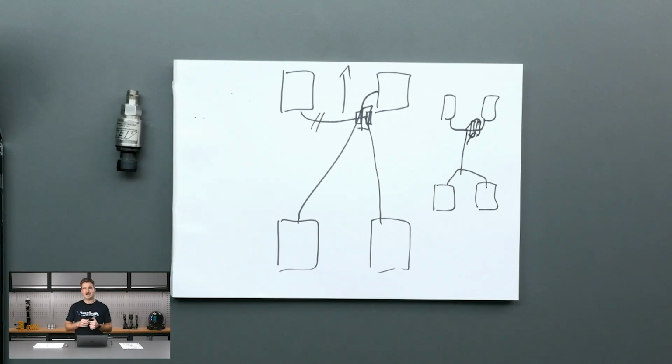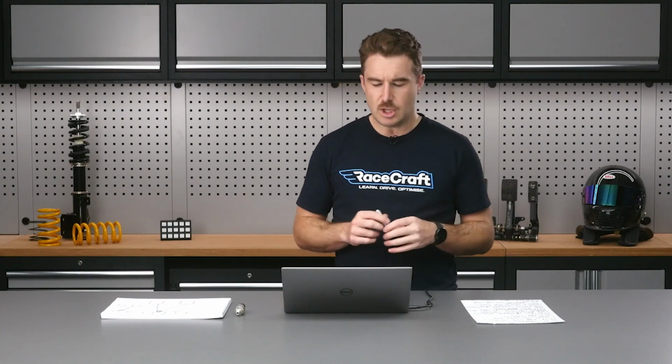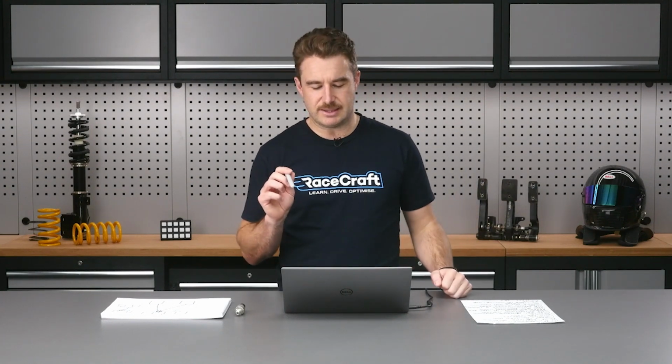So normally when you're modifying brake bias, you want to change the amount of braking force distribution you've got in the front axle with respect to the rear. If you had diagonally plumbed systems, then you wouldn't be able to do that. You'd only be able to change the diagonal split, not the front to the rear split. So this is why in a motorsport context, we almost always have the axles split front to rear like that, and that's certainly by far the most common thing you'll come across. So if you are looking at making changes to your brake system or plumbing brake pressure sensors in, that's just something to be aware of: taking note of how your particular car is plumbed and what that means for your situation.